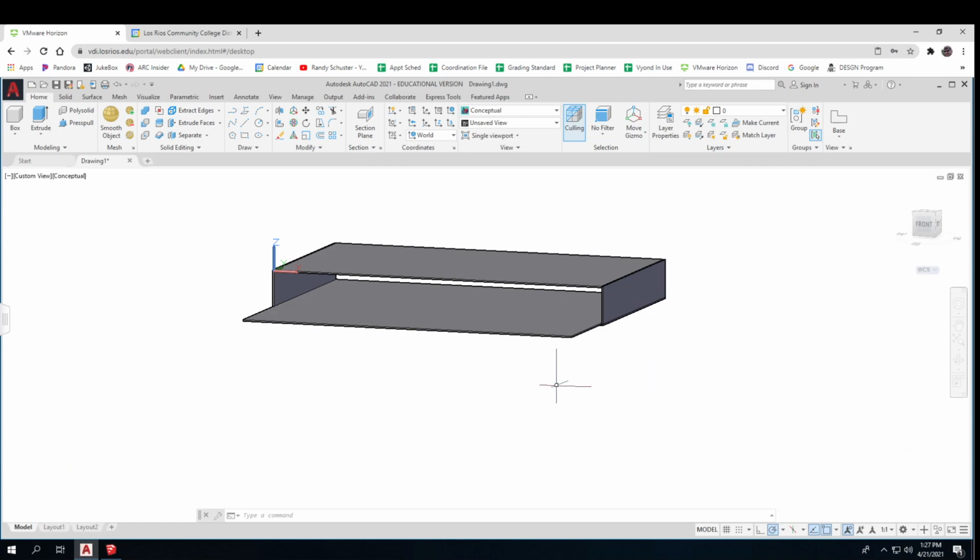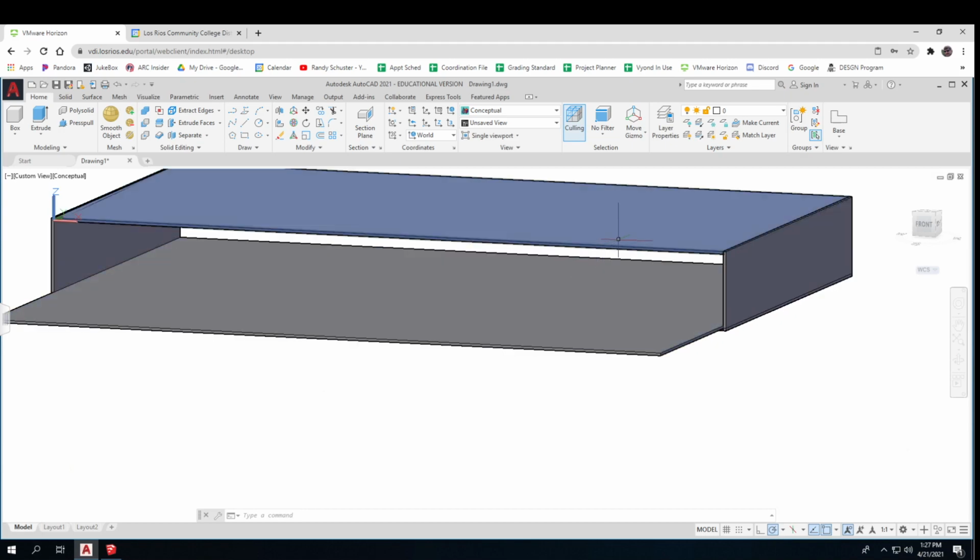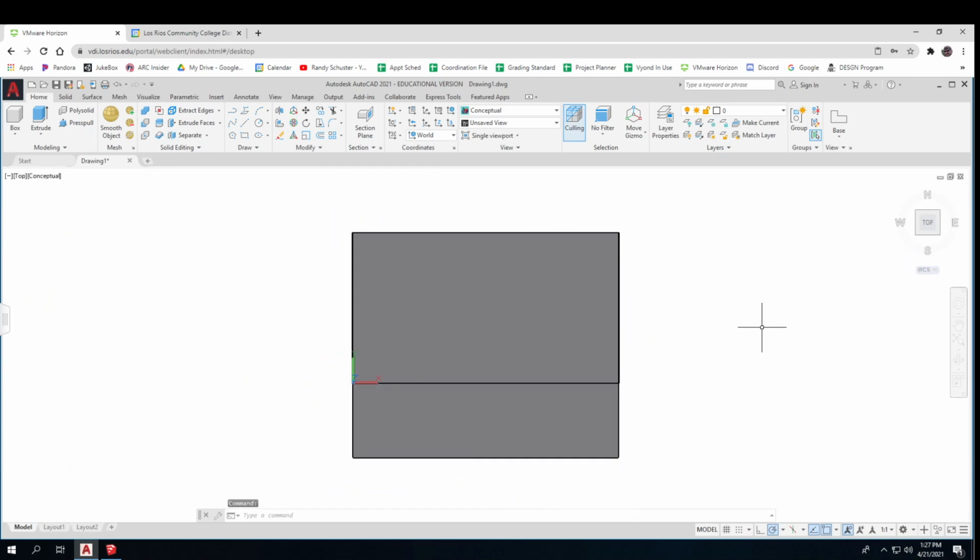Now, here's the other thing: we know that sheet metal is a little bit flimsy, right? This would sag under its own weight. So that's where you start thinking about how could I stiffen it up? And if you put a little bend on a piece of sheet metal, it's really, really strong. And so how could I put some bends on it that aren't really in the way too much? Well, one way to do it, which is a really cool way, I'm going to show right now.